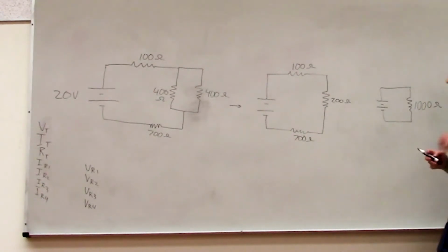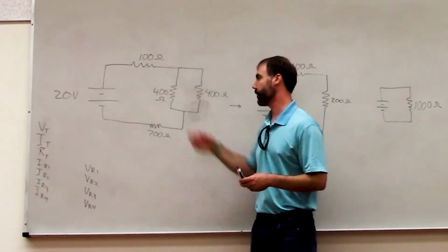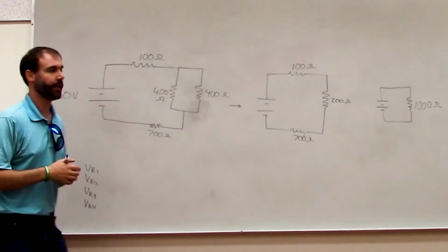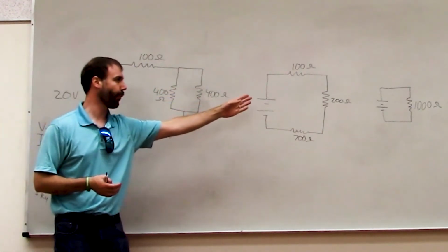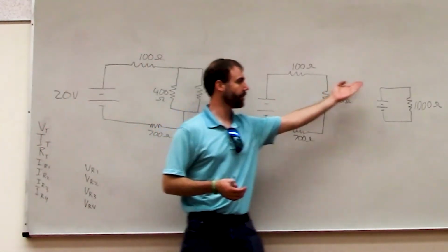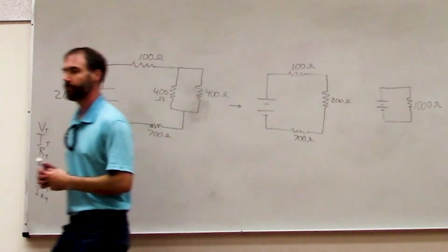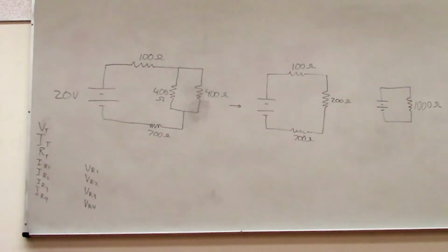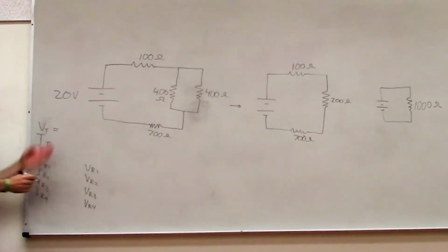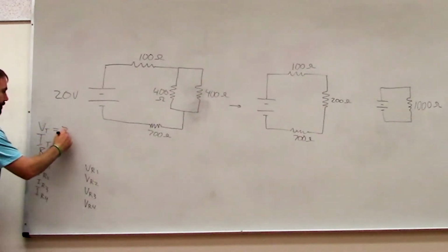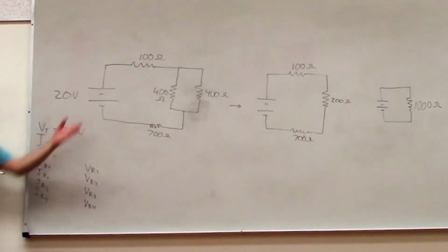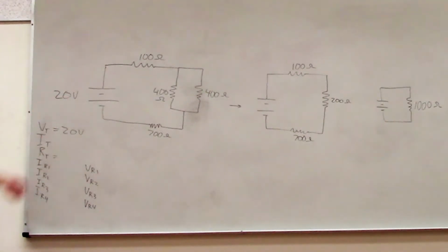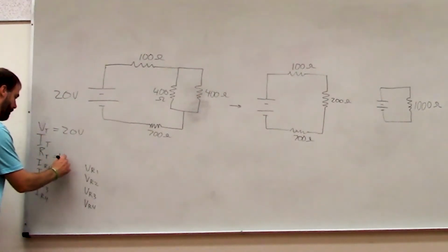So we took this complicated series-parallel circuit and we just looked at it step by step, right? We looked to see if there were any elements in series or parallel, and then we simplified whatever we could, and we just kept going until we got down to a single resistor. Okay? So now we can answer how much voltage we have, right? The voltage is just the voltage from the power supply, so that's 20 volts. What about the resistance? We can put that down now too, because we figured that out. So that's 1 kiloohm.